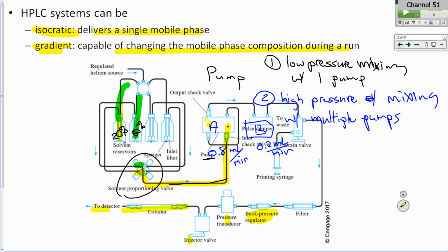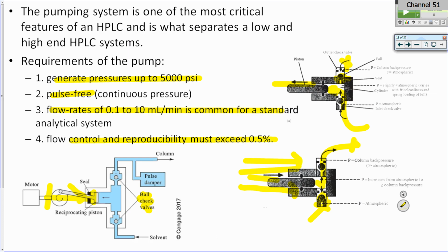So one of the things that's in these pumps, typically written on top of it here, is called a pulse dampener. The pulse dampener is typically a liquid area where the middle has some elasticity. The idea would be like putting this inside of a balloon, so the balloon could expand and absorb the pressure pulse, yet the outlet would be at a similar pressure as we could keep it. So pulse dampeners are standard on instruments as well.